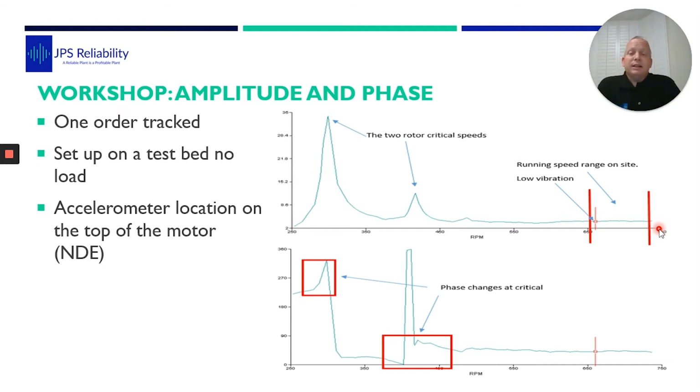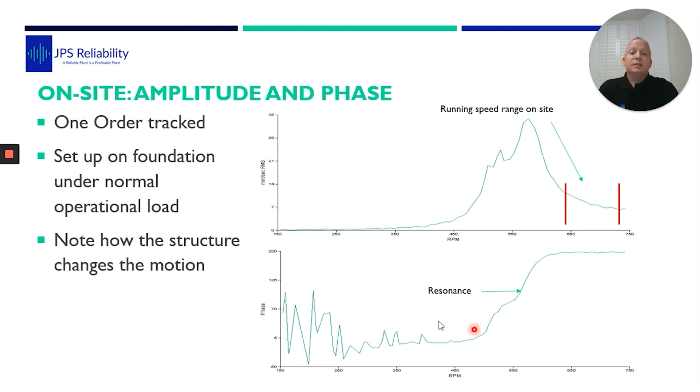So we confidently say to them, there's a resonance issue. It's nothing to do with the motor. The motor is a force, but it's causing the bed plate to move, which is causing your motor to twist like this. So this motor went back on site, and we did a follow-up test. And here we have these low range 180-degree changes.